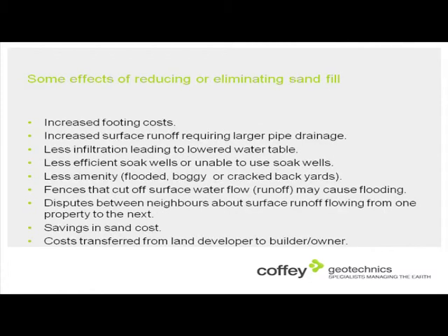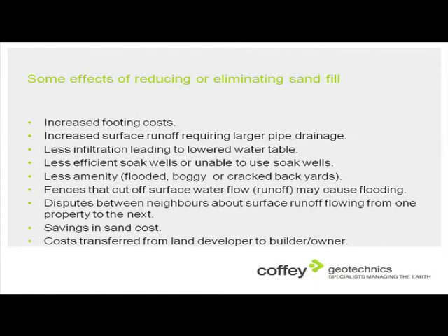Some of the effects of reducing or eliminating the sand fill: well, what you save on the sand, you're going to pay some of it at least in extra concrete and steel, and certainly the trades in Western Australia are not set up to do something like a Class M footing. You ask someone to dig a trench 800 mil deep and put steel in the bottom of it, and they all go, ooh-ah, even though we do it in other states. But we've got a system in Western Australia where everybody can dig a trench 300 mil deep, and it's easy.